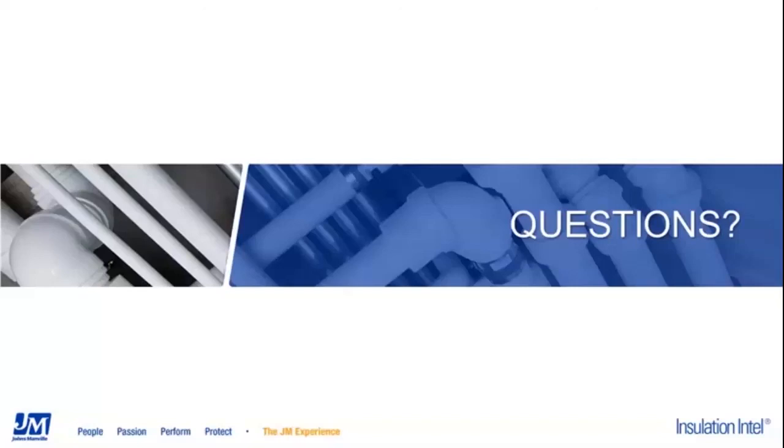And as Heather just mentioned, we do have an installation guide on our website, and that shows specifically both how to install and how to point the overlap, as well as how to properly put the sealant and the type of sealant that we would recommend using. Alternatively, if you have access to industry publications such as the MICA Manual, that one will also provide you with guidance on that. But going back to the original question, absolutely, the metal jacketing can be installed to prevent the water intrusion, and there are practices in place.